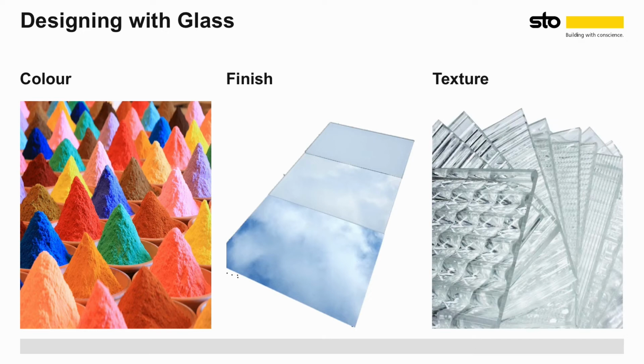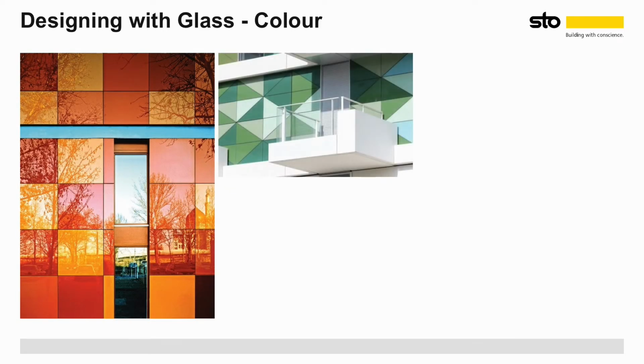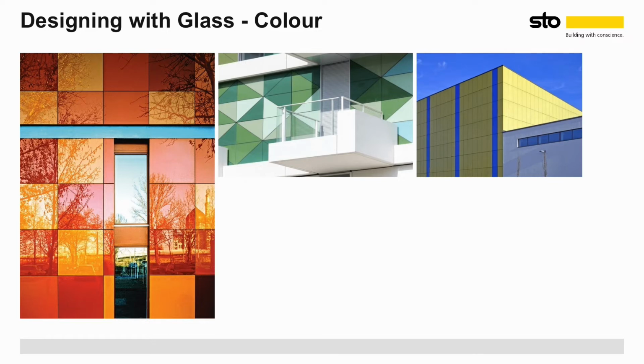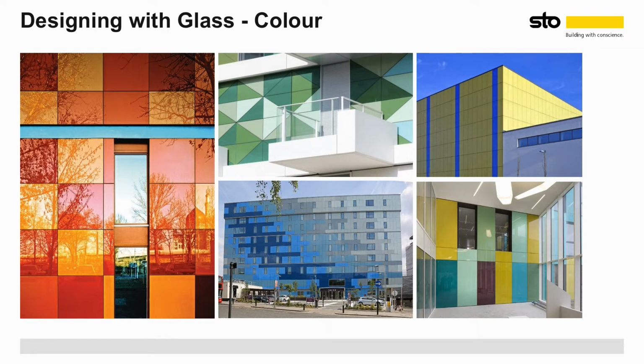Textured glass is also available, adding a three-dimensional element to the surface. Glass Rainscreen panels are generally coloured. It is important to choose a system where the colours are fused to the back of the glass and applied before the toughening process. The coloured enamel melts into the glass at over 600 degrees Celsius. This enamel is colour-fast and permanent. Avoid painted glass, as this may not be as durable.